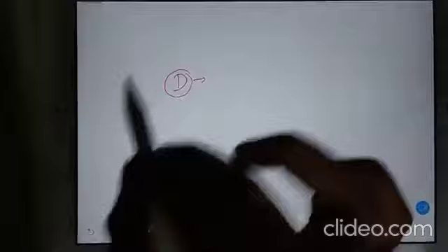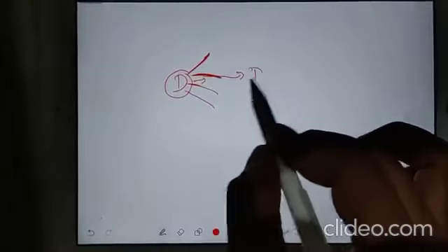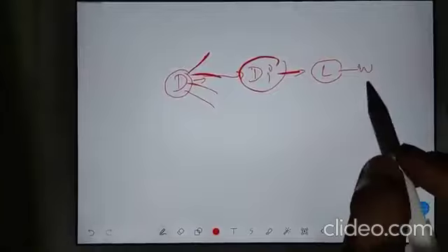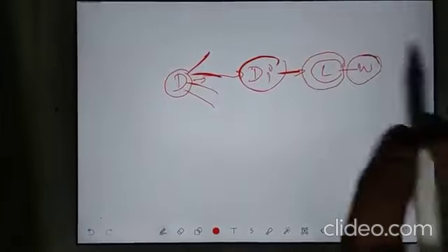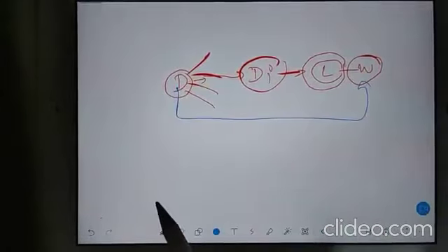Drag is nothing but the total drag. There are so many types of drag. In that, one is CDi, I mean Di, induced drag. Induced drag depends on lift, and lift depends on weight. How much lift you produce depends on the weight. So now the question is, what will be the mathematical relation between drag and weight?